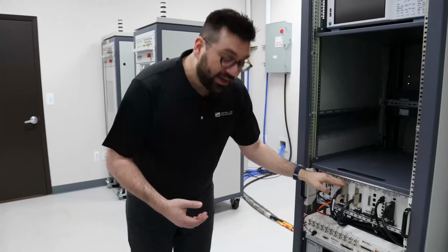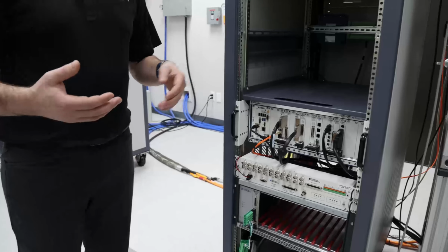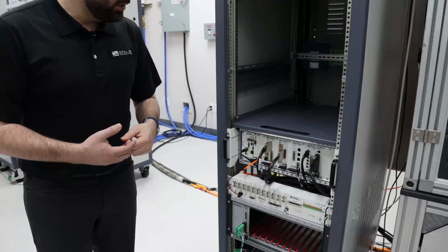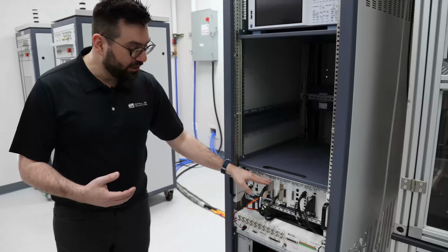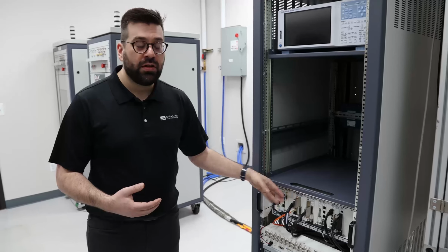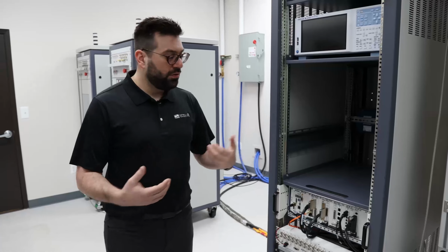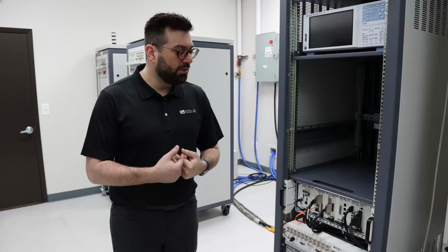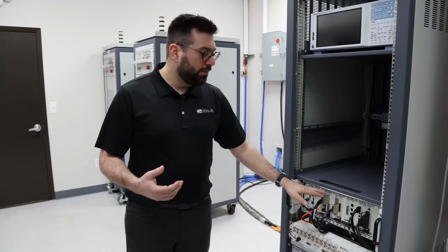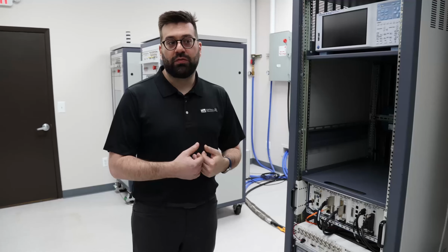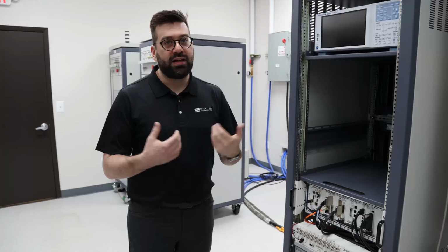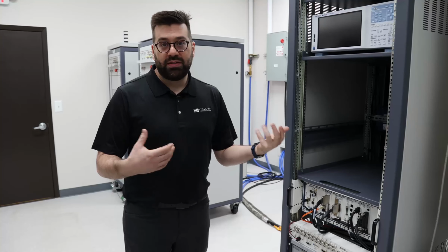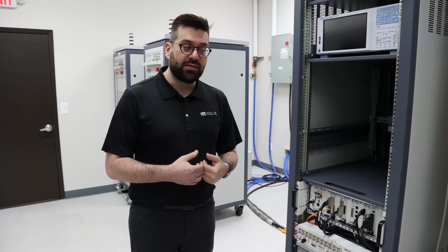And then we also have a lot of low-level signals. We can use them for temperature sensors, but especially we measure the voltage to close the loops to the inverters. And we can generate resolver signals as well. In this case, both DNV and OPAL-RT have the encoder machine. We're both capable of simulating the resolver or encoder signals, but OPAL-RT brings you more flexibility on the resolver signals to create faults, disturbances, and add noise to your resolver signals if needed. During the live demo, we'll see how the machine operates with the OPAL-RT systems.